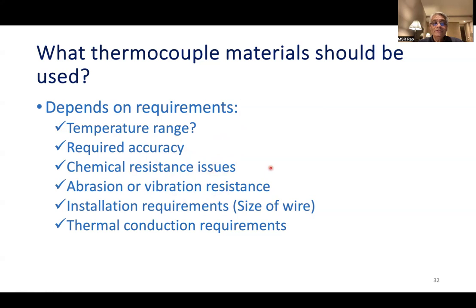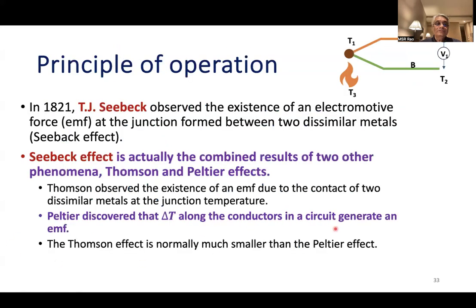Abrasion or vibration resistance is another important property that you need to consider. Another is to properly install, because these thermocouples always need to be extended from the furnace endpoint to the measuring meters, that is typically an old meter. So you need to take care of those kinds of installations, and what suitable wires have to be used. There are also thermal conduction requirements.